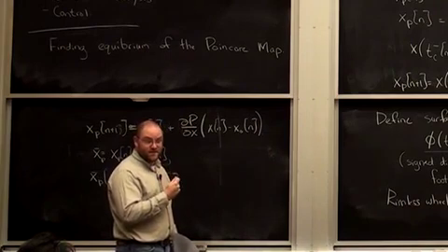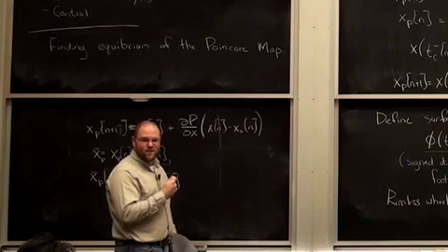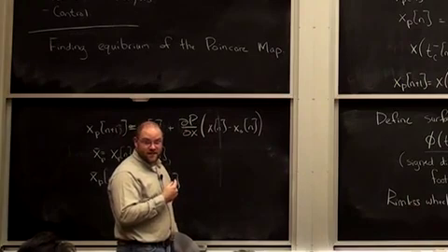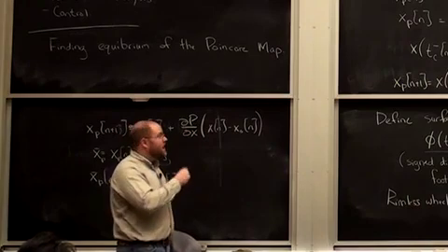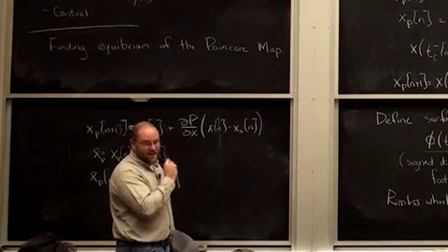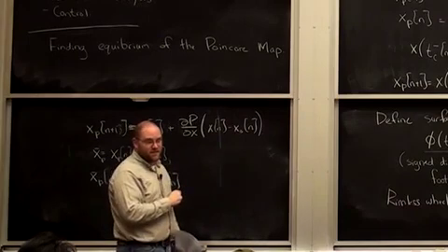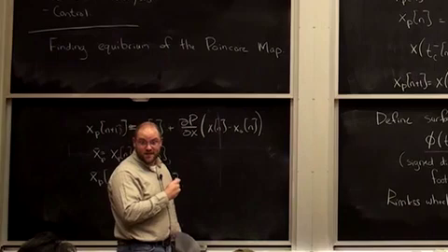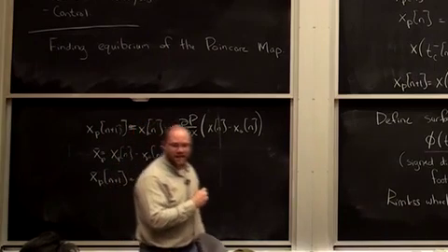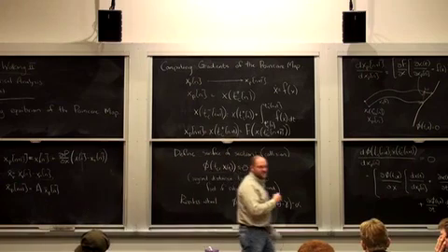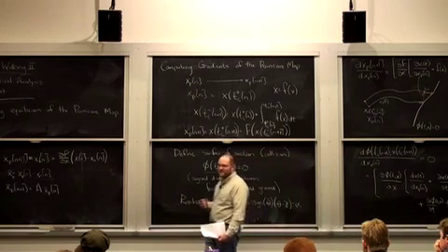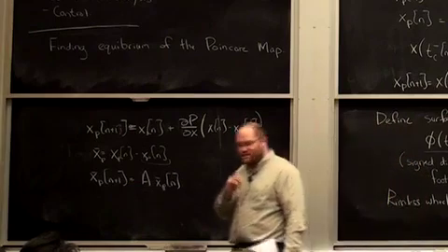What does that correspond to physically? What do I even mean by two-step on the Poincare map? It's like in between two different points. So x of n plus 2 is going to equal x of n, but x of n plus 1 doesn't necessarily. But every other one is going to be the same. So what does that physically correspond to in the walking? It's more of a limp, I'd say. It's some asymmetric gait. These robots start doing a potentially asymmetric thing. Every other footstep ends up landing in the same place, but not every footstep.